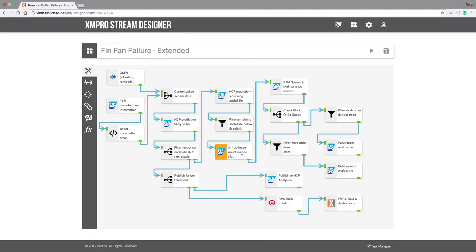the maintenance. So for example, if this was 100 hours, we have a window of remaining useful life. We may find the most optimum slot to do any maintenance is 62 hours. And we would then also go and look inside the EAM system against that specific equipment, identifying critical spares, and see if those spares are available.